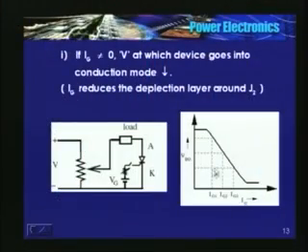Now here I have just shown you the plot of the variation of VBO with IG. Okay. See, here is a simple circuit. I am just closing the switch. Till the device goes into conduction mode, or till the load current through the device is higher than the latching current, then I can open the switch.